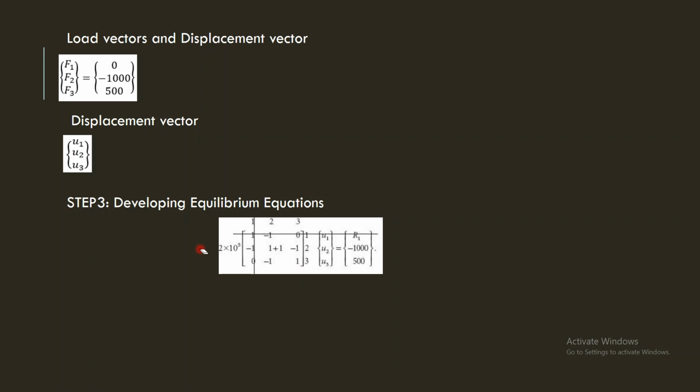Okay. So if you remember, the global stiffness matrix, this is the stiffness matrix globally, multiplied by the nodal degrees of freedom, that is the displacement vector, U1, U2, U3, and thereafter that should be equal to F. So the F positions that we already took, that is 0, minus 1500, and this should be 0.